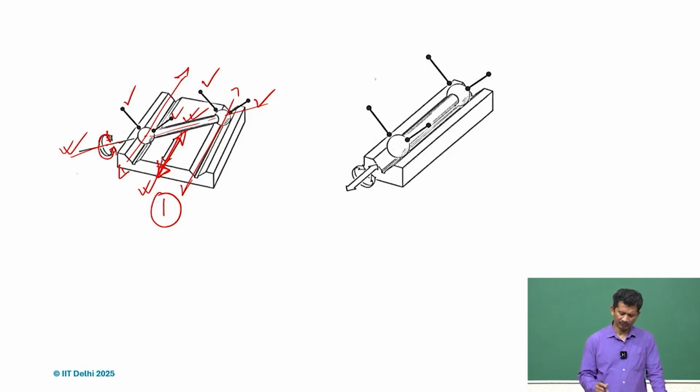At the same time, if we put the same object with the two ball ends on a single V groove, again we have this constraint defined. So, two contacts at each ball end, but we realize that yes, it can move along the V groove axis, and at the same time it can also rotate. So, very easy to visualize.